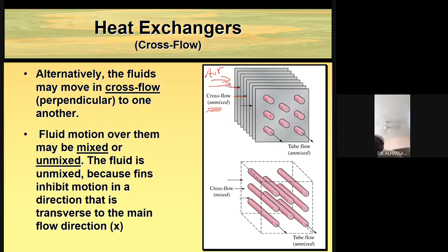Now there are tubes that pass through the plates. So these are tubes 1, 2, 3, 4, 5, 6, 7, 8, 9. These tubes pass through the plate, and we have hot fluid flowing through each particular tube. As the cold air flows across the tubes, the fluid is forced to cool down. So this is a cross flow situation. The cold fluid is moving in this direction, and the hot fluid is moving perpendicular to it.